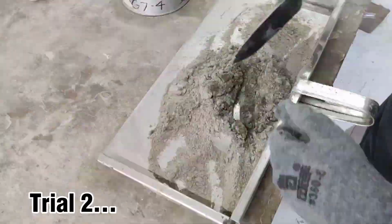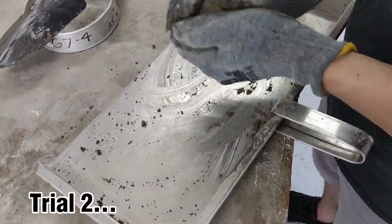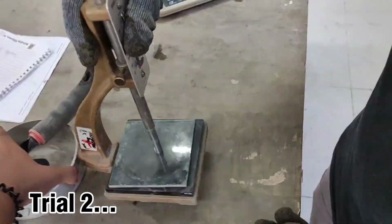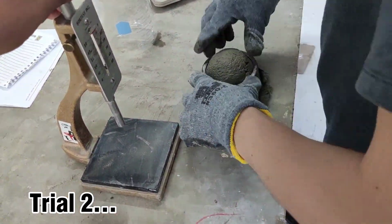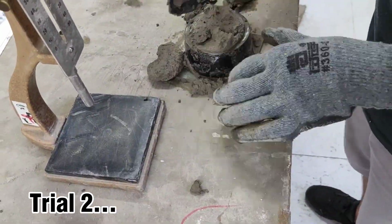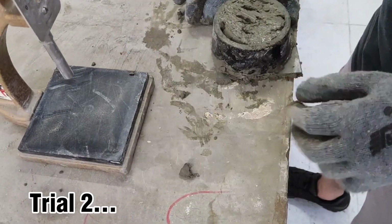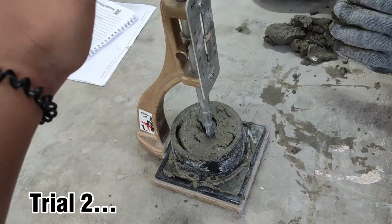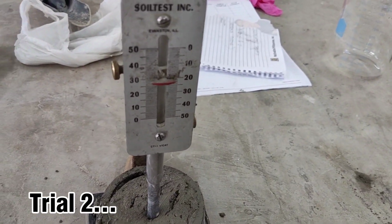Therefore, we then got another sample, but this time added 33% of water, which is 165 milliliters. However, it still resulted in a 22 mm penetration.